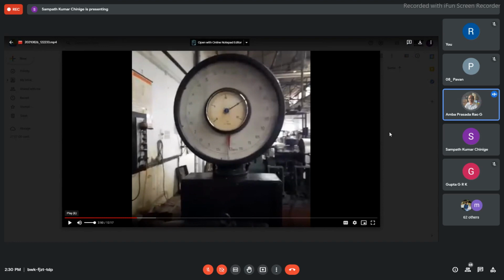T is the maximum torque, and the maximum power is 5 HP safe power, equivalent to 3.68 kilowatts. This torque meter reading here is in kg force meter, so multiply by 9.81, it will give you the torque in Newton meter. N is the RPM, given in revolutions per minute, that's why we are dividing by 60. So 2 pi NT by 60, into 1000, with T in kgf-m times 9.81, will give you the power reading. From that you evaluate the maximum value of torque.